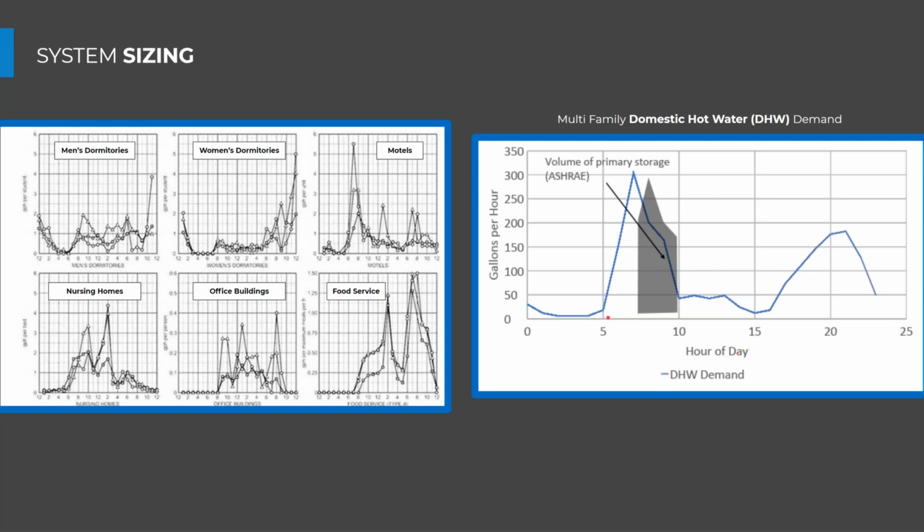So our gas water heating systems typically are sized to recover the storage volume in this peak time of use. So there's a lot of heat capacity or recovery rate required to recover in that amount of time, typically a 3 to 4 hour period. I would argue that with heat pumps, you're going to make better use of your money if you're sizing to run for a longer duration, and you have a large hot water storage tank or a group of storage tanks to store that water, to have a large thermal battery, right?